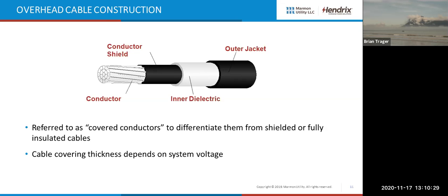We will put a spiral knife into the outer jacket and penetrate most of the inner jacket and turn it in a spiral fashion. And that inner layer will be easy to strip and it will peel off the semicon layer at the same time.